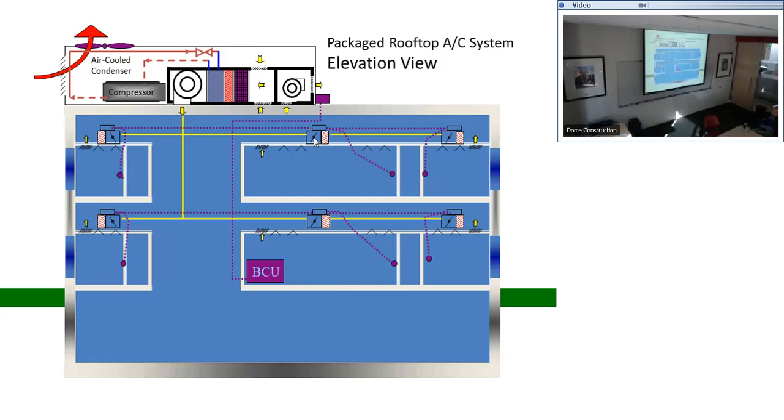So I'm going to reheat the exterior. Code makes you go down to a certain CFM per square foot, 0.3 to the supply, but they make you go down to a certain number before you can reheat, because we're about saving energy. Typically this unit is always producing 55-degree air. You can do some reset. Just say this was getting 1,000 CFM. You don't want to heat all that 55-degree air up to 70 to heat the zone, so you modulate it down. And that's the VAV box doing that with the reheat.